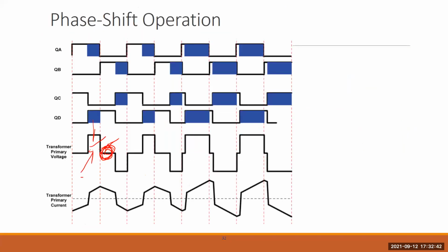So during the design, we have to take care of this portion, how this circulating current can be minimized to result in high efficiency. At full load, it doesn't affect because at full load the duty cycle is 50% and the phase shift is 0. At light load, it affects when the phase shift starts increasing.